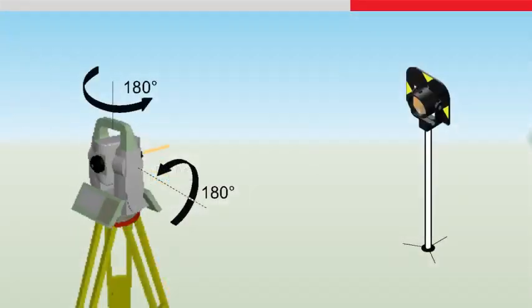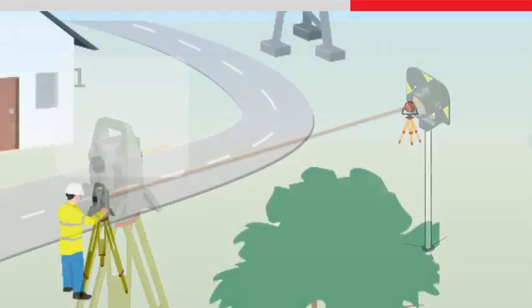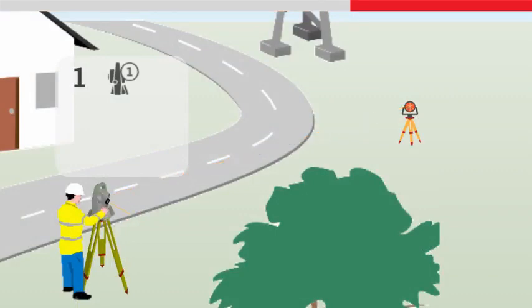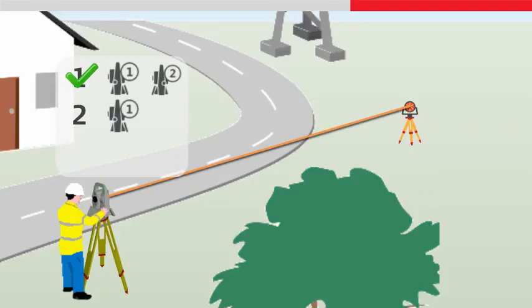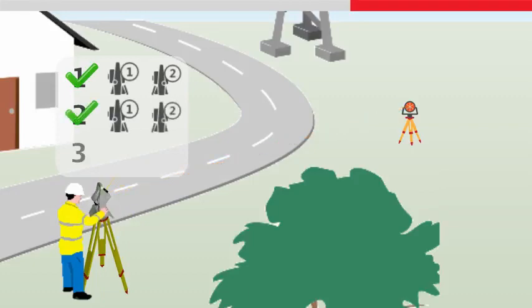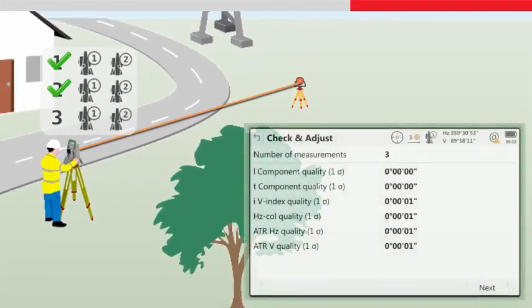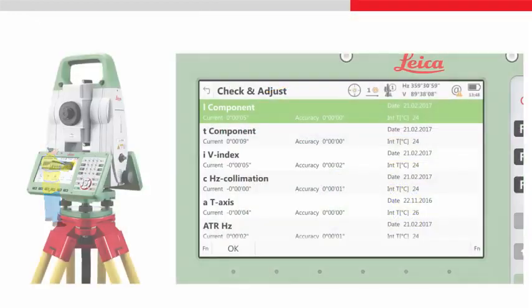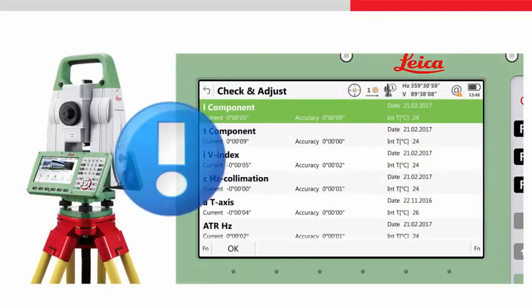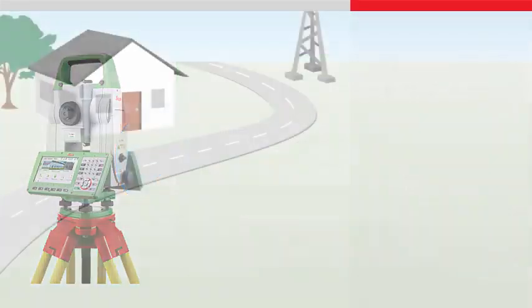As you will see, all calibration routines consist of two-phase measurements. To achieve precise calibration values, the two-phase measurements should be carried out at least 3 times in a row. If the desired accuracy is not achieved, additional two-phase measurements can be executed to improve the results, or the routine should be restarted. To avoid systematic error sources, the following aspects must be considered to guarantee reliable results.